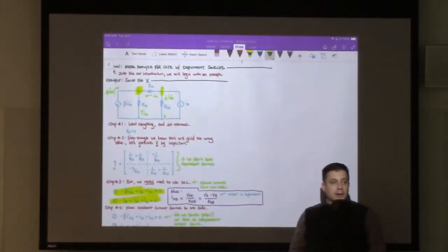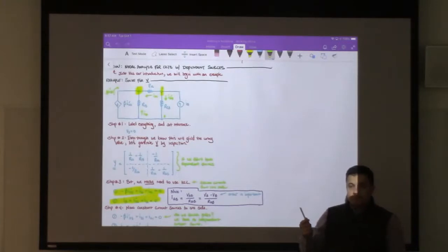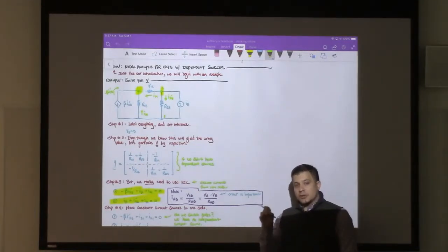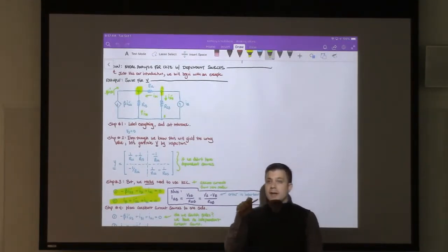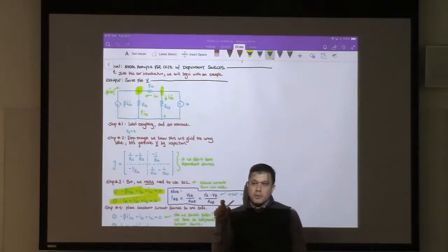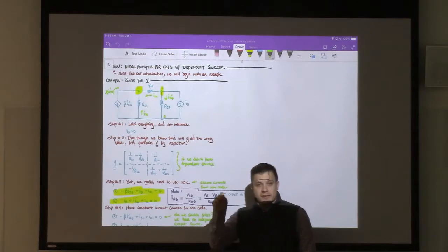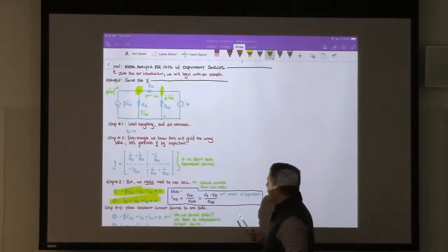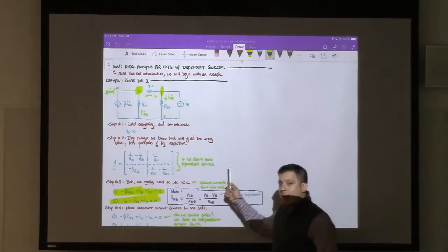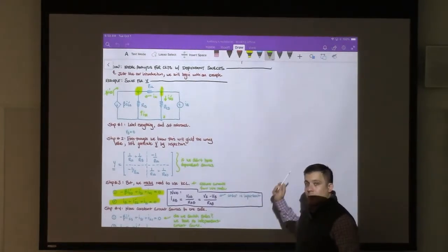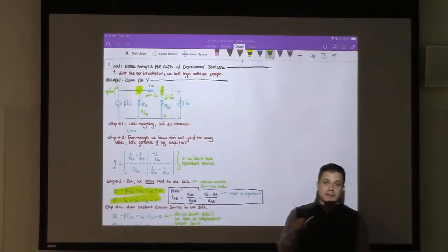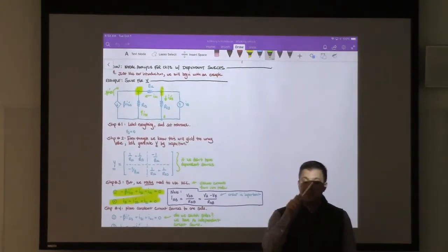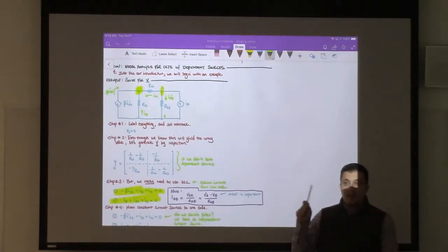Along the off diagonal, the values are negative. And 99% of the time, assuming there's not more than one parallel branch that spans between the two nodes, you put minus 1 over the spanning resistance. So if we're talking about element 1, 4, you look for the resistance that connects node 1 and node 4 and put minus 1 over that resistance.